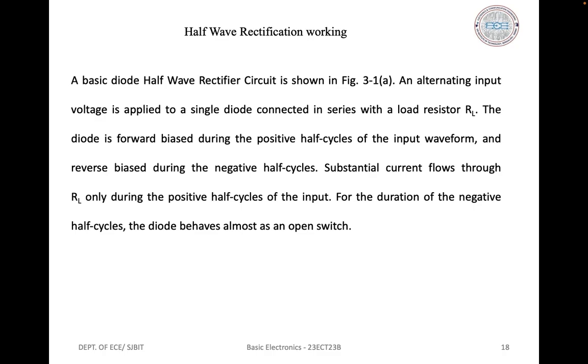The filtering process normally involves the use of a large reservoir capacitor which charges to the peak input voltage level to produce the DC output. The capacitor partially discharges between peaks of the rectified waveform, and this results in a ripple voltage at the output. The ripple can be reduced by the use of RC or LC filters. Power supplies are specified according to the DC output voltage, load current, and ripple voltage.